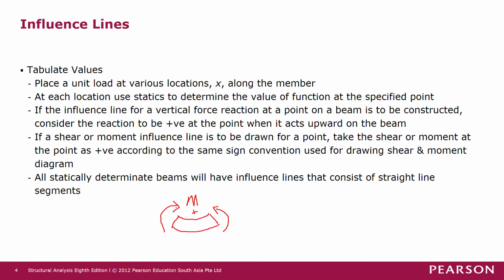On the left hand side of the element, we put the moment as clockwise, if we cut across the section and isolate this part of the structure as a free body diagram. And if we cut across a section and the bending moment is on the right hand side of the cross section, then we put an anti-clockwise moment as the bending moment. So these are all positive bending moments, depending on which side of the element we are considering.